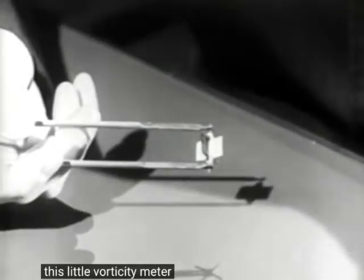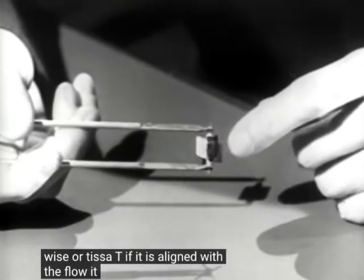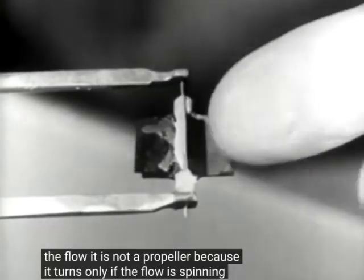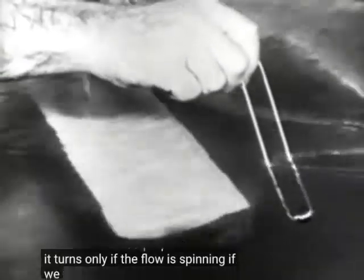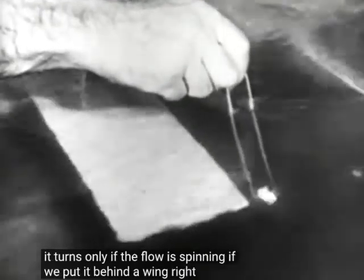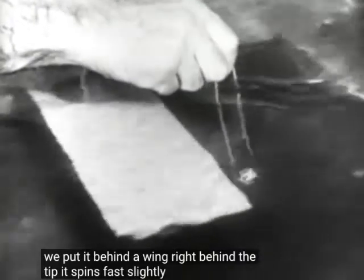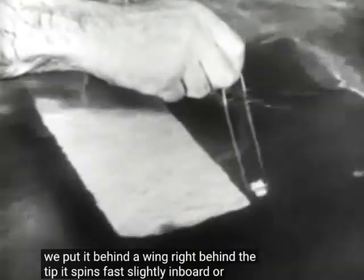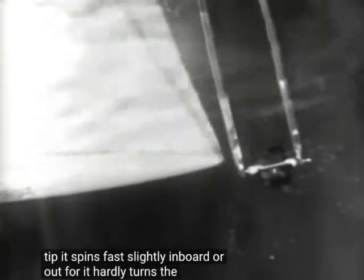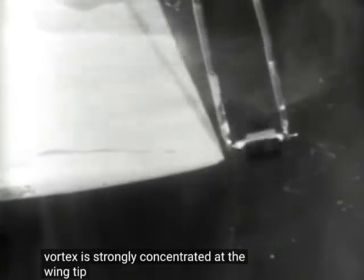This little vorticity meter shows streamwise vorticity if it is aligned with the flow. It is not a propeller because it turns only if the flow is spinning. If we put it behind a wing, right behind the tip, it spins fast. Slightly inboard or outboard, it hardly turns.